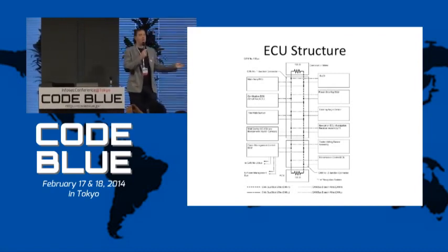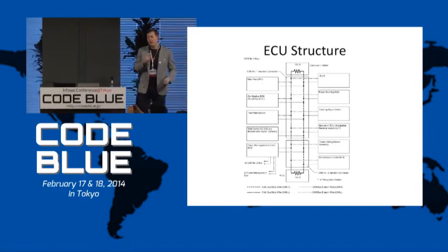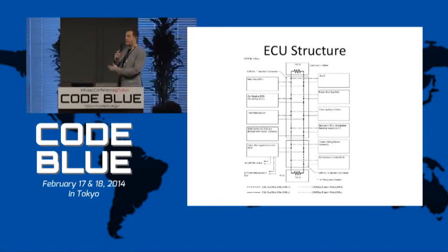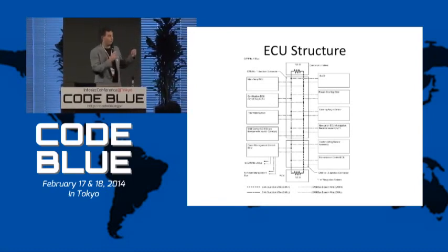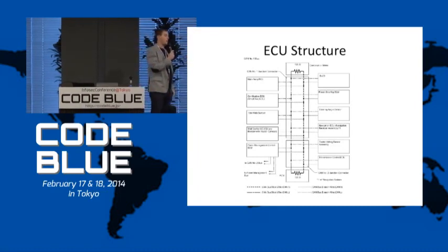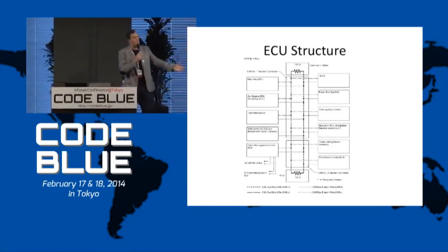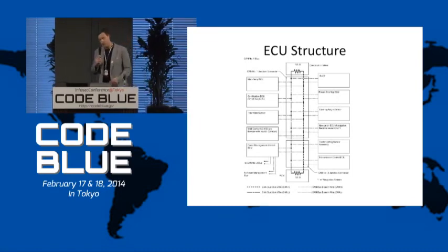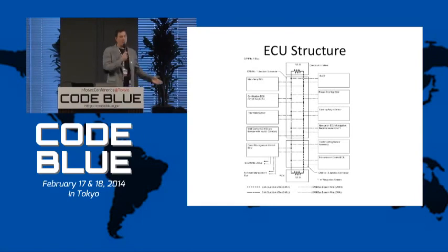It's not like they happen ad hoc. They're just always happening. And the only way the other ECUs know what to do with it is they have an ID and a value, which we'll talk about. And it'll just say, hey, I'm interested in that. I'll consume it. Or here's the IDs I spit out. It's really quite elegant and quite simple.